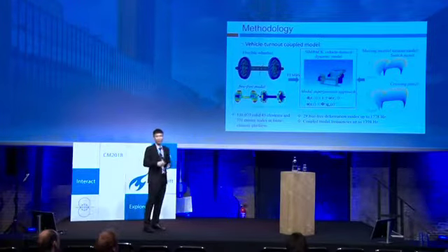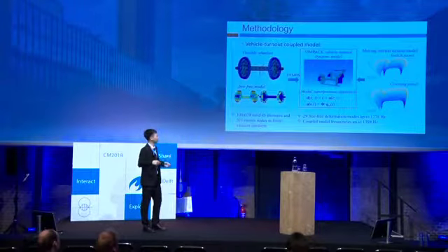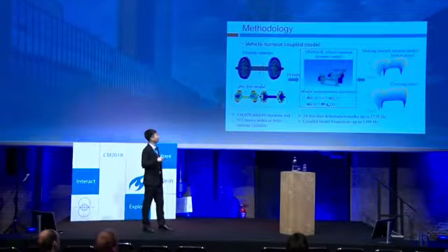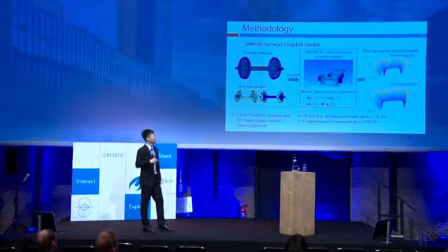Because the wheelset is subject to the constraint by the axle boxes and the primary suspension, the eigenfrequency of the vehicle and the flexible wheelset coupled model is obtained. And the 29th coupled mode, whose frequency is up to nearly 1,400 Hertz, is considered. Finally, the smooth cross sections of the turnout are obtained by interpolation, and they are used as the inputs to the multibody dynamic turnout model.